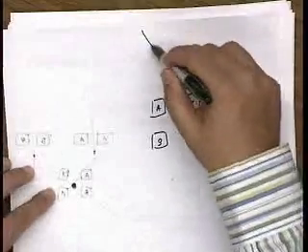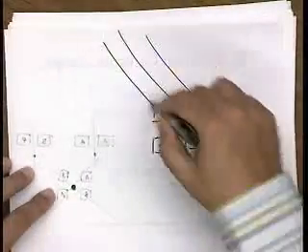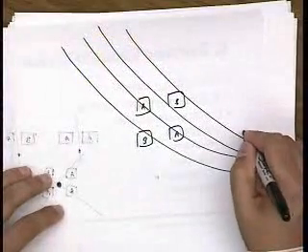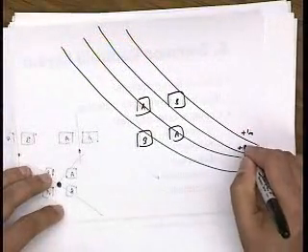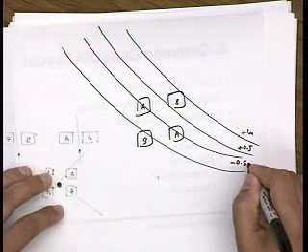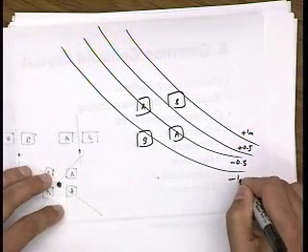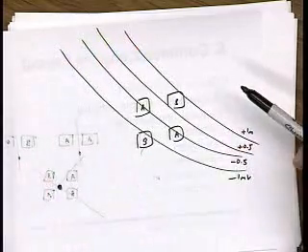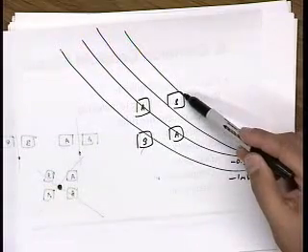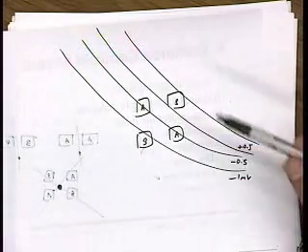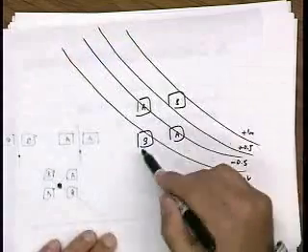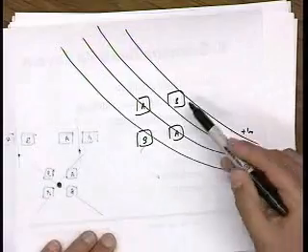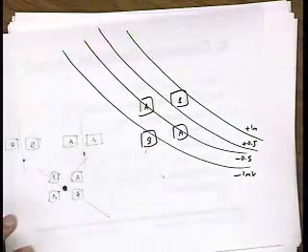there could be like a large-scale process gradient. So let's say these are curves of constant Vt. So this is plus 1 millivolt, this is plus a half a millivolt, maybe this is minus a half a millivolt, and this is minus 1 millivolt. So this device has 2 millivolts higher Vt than this device, right? But the average Vt for this device is about 0 millivolts away, because half of it's 1 millivolt higher, the other half is 1 millivolt lower.